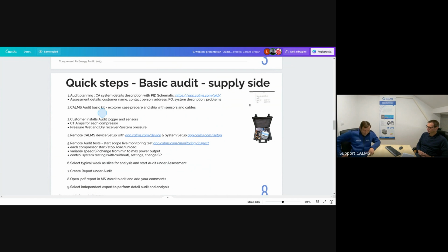What I know is that we are experiencing pressure drops. Guys in production have been calling me. I have set the compressors to run at 7 bar, and as far as I know, the compressors are 7 bar compressors, so I do get 7 bar air. But in production, they say it's dropping down to almost 6 bar, and they're having problems with the production. Therefore, I would like you to find out which one of these compressors is not giving 7 bar, and I will be looking to buy a new compressor.